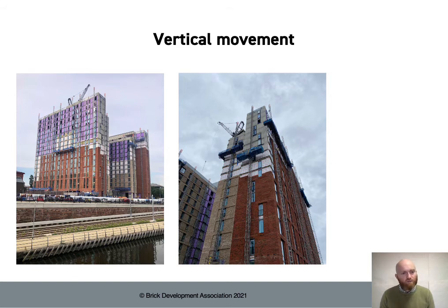That's the same then for your movement joint and your normal bed joint. You color match the mastic, you have that continuous horizontal movement joint, and again you just don't really read it as anything different from your normal mortared bed joints.